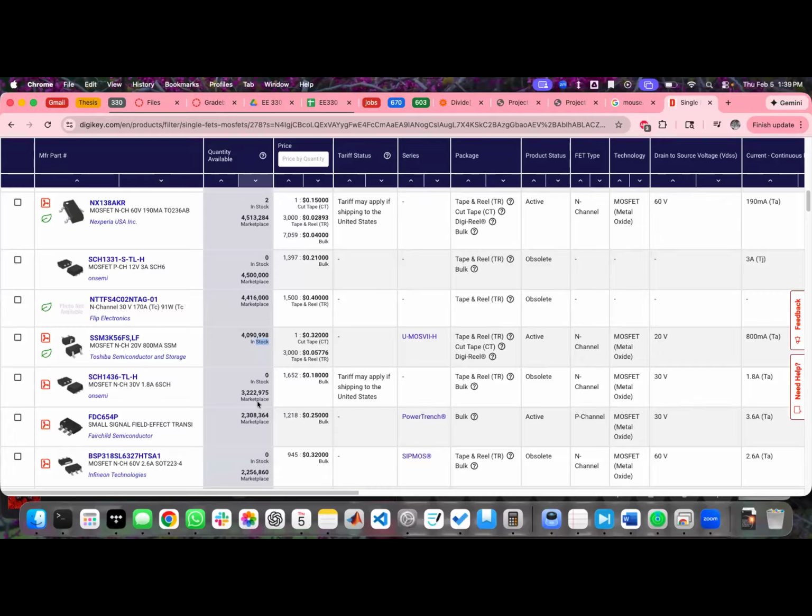A lot of the time you'll go and it'll feed you some random Zener diode instead of a general purpose diode, and it's going to behave kind of funky, and you're going to be like, why is it doing this? And you're going to spend a ton of time debugging why it's a Zener diode and spend less time debugging your circuit as a whole. So this is my general recommendation, especially if you go to senior design. This should be pretty helpful.